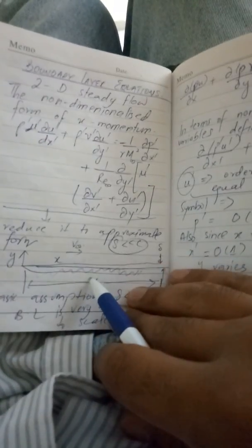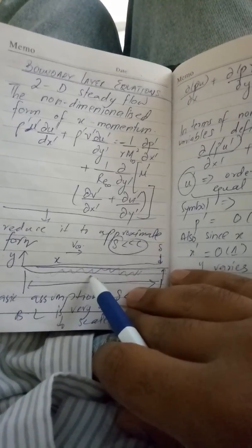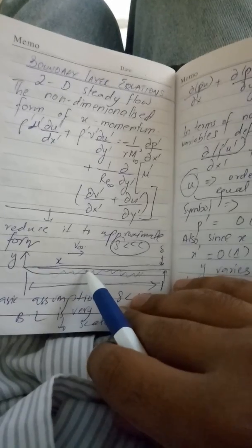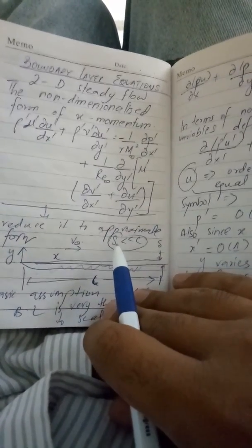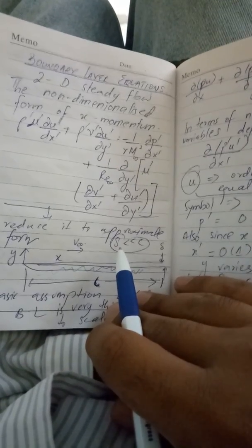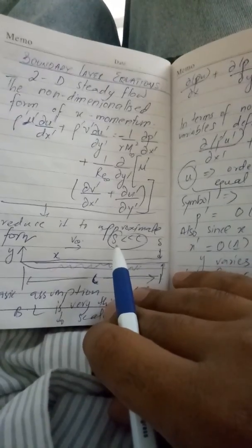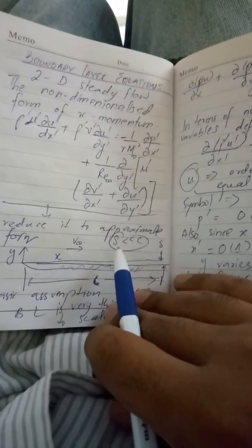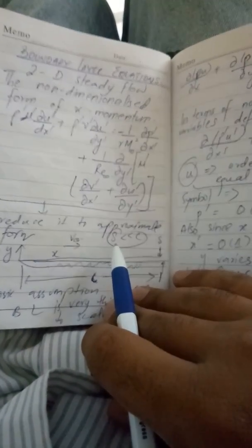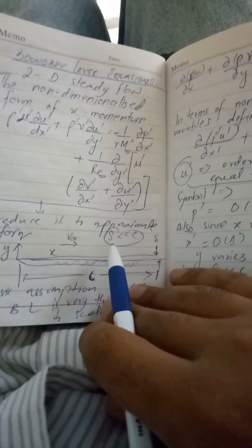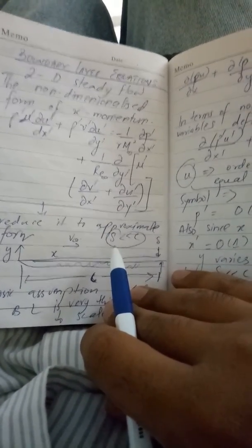We have taken the assumption that lambda, the boundary layer, is very small as compared to the scale of the body. Understandable. We have taken lambda in terms of y, and when we talk about y, we have talked about v as well. When we talk about x, that is the x-axis, we have talked about u, which is the velocity. Multiplying rho, the density, into velocity, we get the momentum. We have talked about the x momentum, and we talked about the y momentum by taking out the first order derivative.